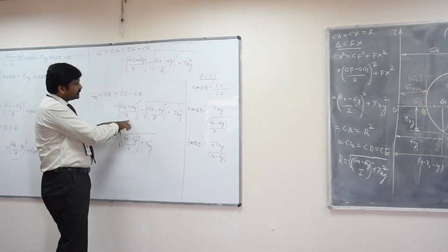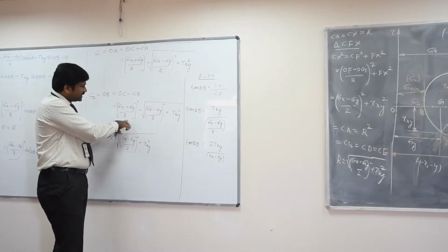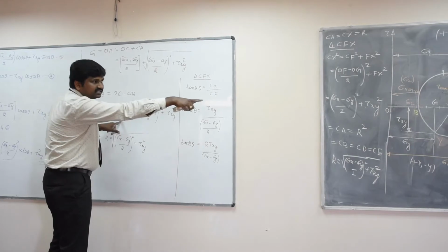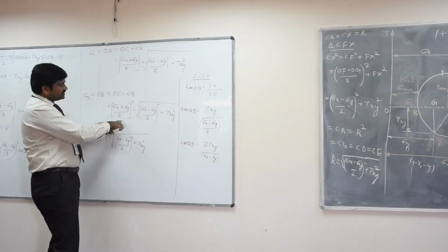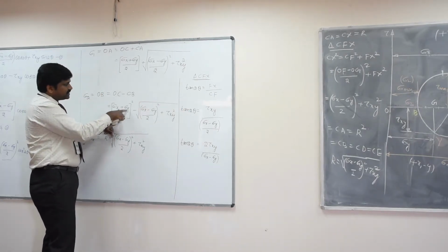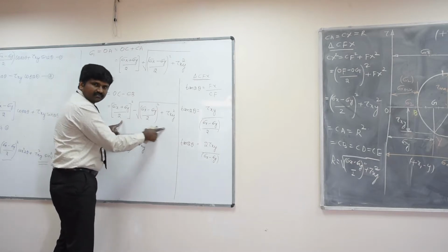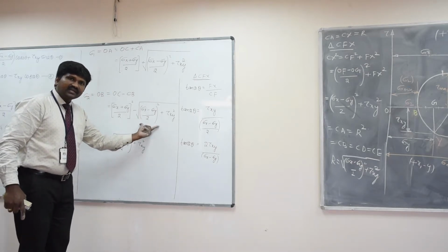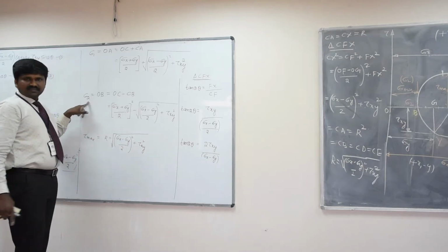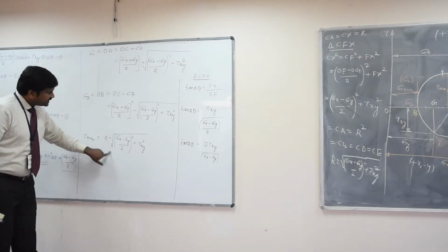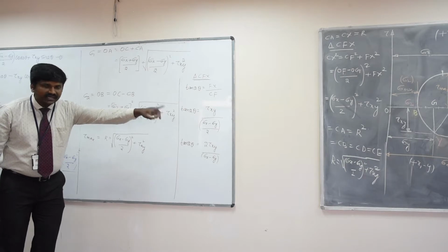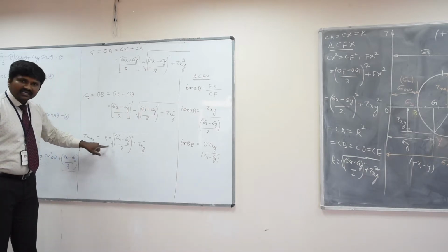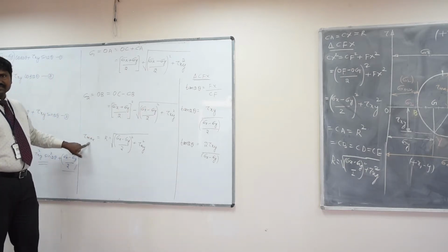So OC is what? OC is the center of a Mohr circle. Then what is CB? CB is the radius of a Mohr circle. So center of the Mohr circle, sigma x plus sigma y by 2, minus the radius of a Mohr circle. So you recall this equation which was derived analytically, which gives the minimum principal stress. This I did not explain again because it was explained earlier. The radius of a Mohr circle directly gives you the maximum shear stress.